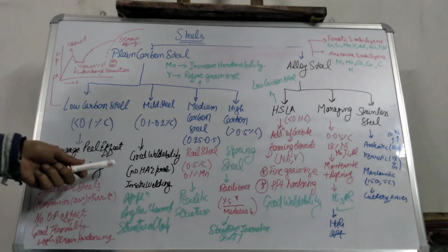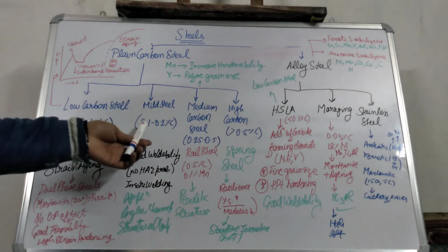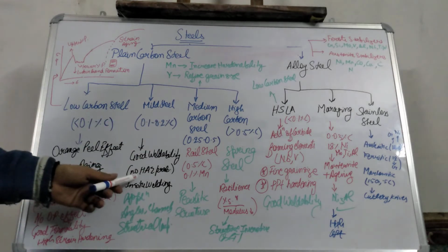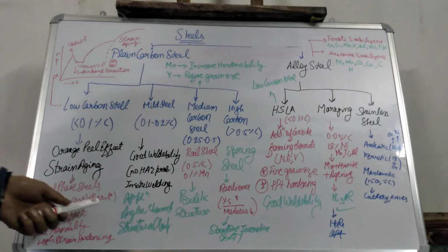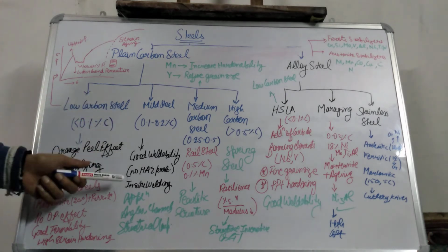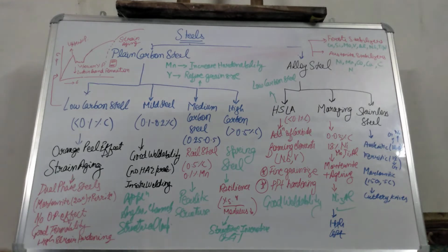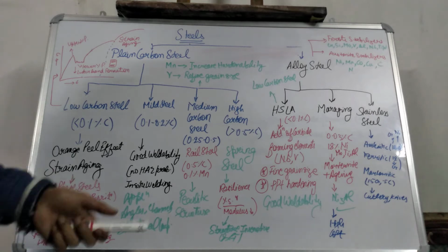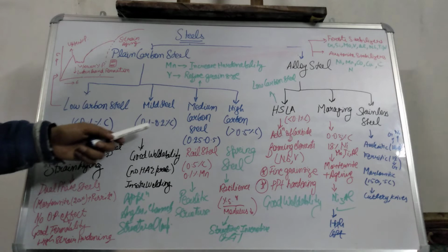Because of that there is a probability of formation of martensite, which may weaken the material and make it brittle. But due to the very low carbon content, martensite formation in the HAZ region is avoided, and no further treatment is necessary in the welding of mild steel. So in all the structural applications where it is not possible to take the material ex situ and give it any treatment, in the as-is condition, it is most widely used.